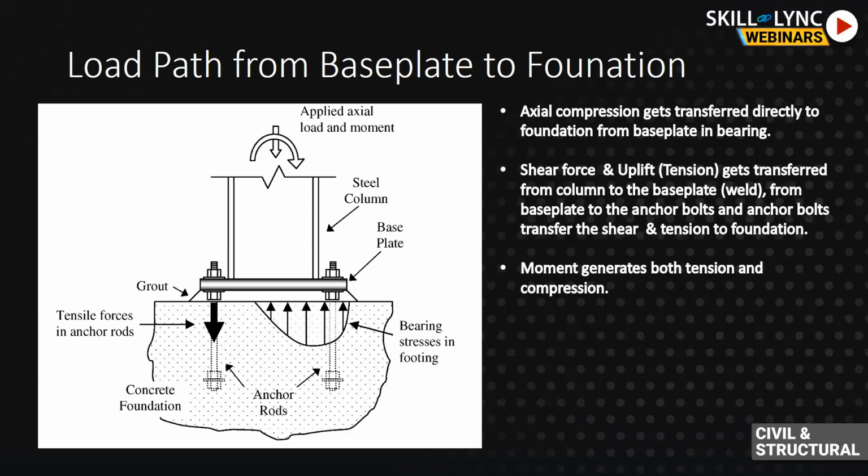When it comes to the shear force and tension, the shear force and tension get transferred through the anchor bolts, but how does it reach the anchor bolt? The columns are basically welded to the base plates.